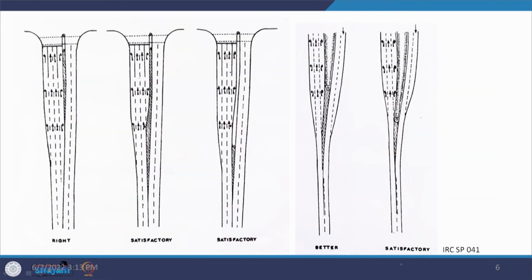Here you can see some examples being given. What you find is that there is a 4 lane divided system. So, we have 2 lanes here, we have 2 lanes here, and the traffic here is moving in this direction. So, this traffic can keep moving in those 2 lanes, but when we are coming to an intersection, moving in the direction towards the intersection, we have done a segregation of left turning as well as right turning. So, this is a right turning and this is a left turning condition being created, and there is a channelizing island being provided here,